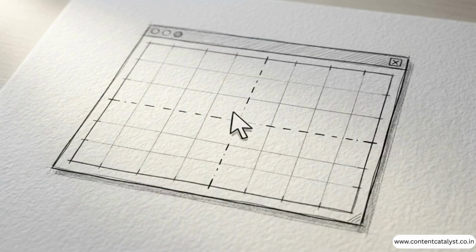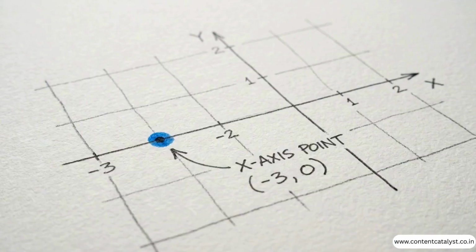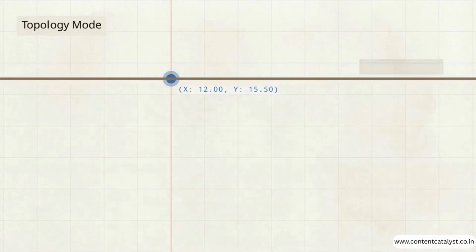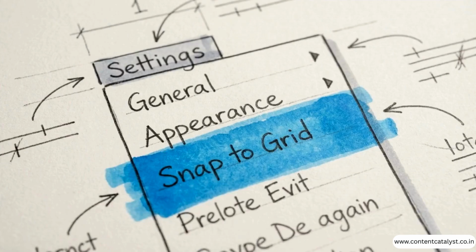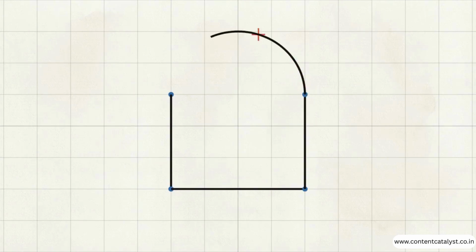Step 1 is establishing the shape of the terrain. If you are working with a flat surface, simply input a single point in the interface. The program will automatically generate a flat terrain line across the workspace. Next, we draw the tunnel itself. Go to Settings and turn on the Snap to Grid function. This keeps your geometry precise. Use your mouse to draw 3 connected lines for the walls and floor, and then cap the top of the structure with an arc.